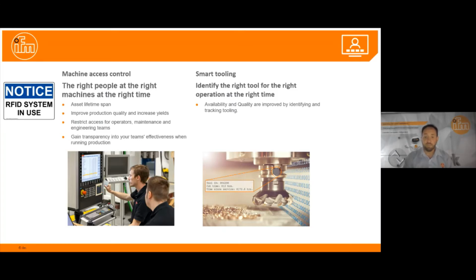With RFID, we could tag all the change parts and the positions that the parts are in, relative to the volume or size of the products that will be produced. After the changeover, at the push of a button, the correct configuration can then be verified through RFID readers monitoring tags that are in place.